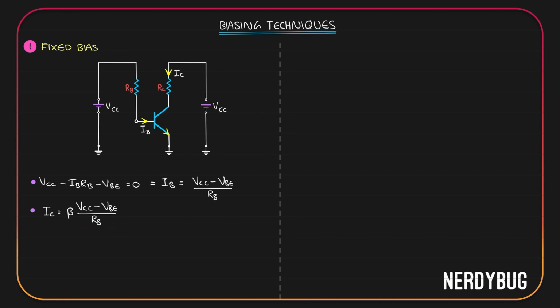Let us now apply KVL in the collector emitter loop. I'll start from this point and go counterclockwise. As I go, I can see VCC from negative to positive. As I go on, I can see there is RC over here. Current flowing through RC is the collector current and it is flowing in this direction, which means RC should have positive potential here and negative potential here. It is opposite to the direction of VCC, so I will write minus ICRC.